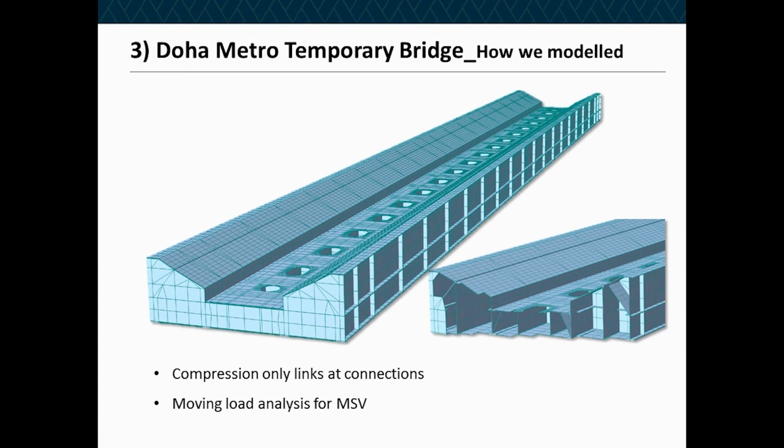And then this was the plate model that was built up after that. What I've tried to do here is take a bit of a section through by deleting some of the elements so that you can see the inclined stiffeners that we had in there to take the MSV wheel loads, the inclined stiffener in the top. There was a plate that ran through at this level to tie the whole thing together. And the plate model itself gave a very reliable stiffness profile and deflection results.